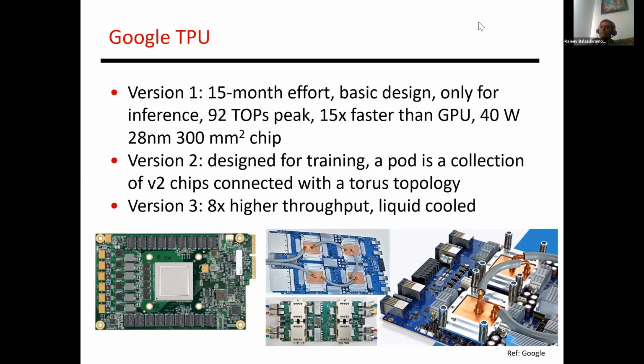If you look at the architecture itself, it borrows a lot of the concepts that we had seen in academic papers. What is really insightful about the paper is Google's perspective on this whole problem, and that's what I want to spend more time discussing. Back in the early days of 2015, they realized that they were spending on all these GPUs and doing all this training, and they did some analysis showing that it was worthwhile to invest in designing a chip in-house, which would give them much higher performance than the GPUs of the time and consume less power. Obviously GPUs are designed for something else, for graphics. They have branch predictors and caches, and all of that also gives them unpredictability in terms of performance.